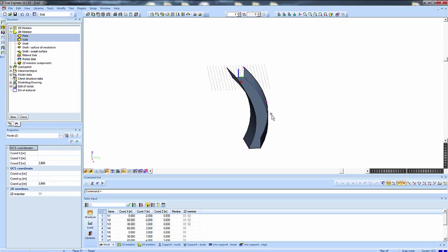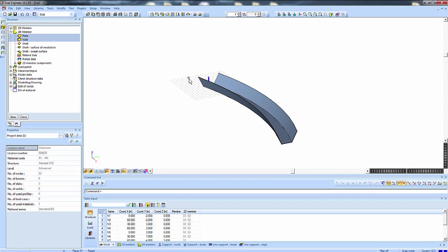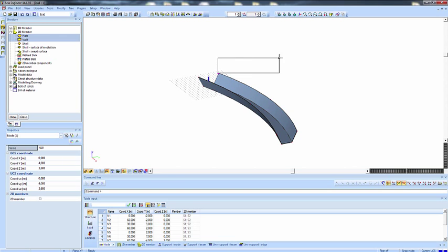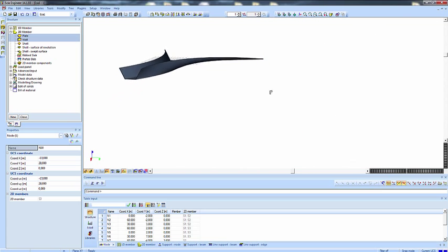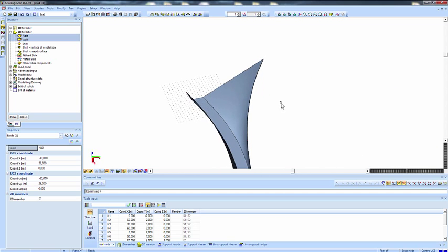I'm going to do the same thing in the other direction. I'm going to say modify move, and I'm going to say the start point is the origin and the end point is 0, 2. This way I've defined a vector which indicates how the node should be displaced. As you can see, I can just easily select points that define the element and just move them. If desired, you can also just select it and move it with your cursor. That is also a possibility. If you want a bridge like this, usually it's not very easy to create.